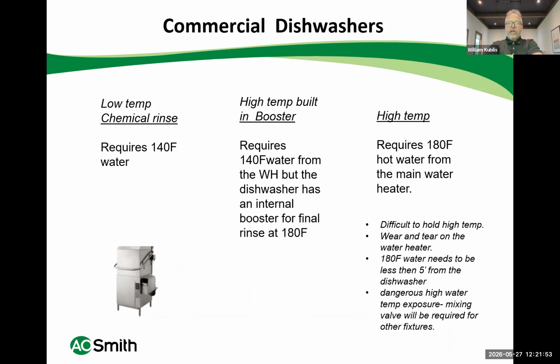Just as a note, because we are talking about restaurants, I wanted to point out the different types of dishwashers and something you should consider in your design. I find the low temp chemical rinse dishwashers are the most common. They require 140-degree water.